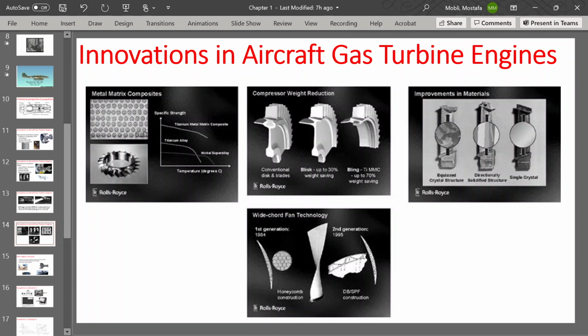And I guess you would assume that one of the main problems they have is the combustion chamber, right? If you are dealing with a micro jet engine, the air molecules are going to become important, right? Because it is a micro jet engine, air molecules are not as small compared to the size of the engine anymore. Also, the fuel-air mixture. All of these things are going to be very important. But how are you going